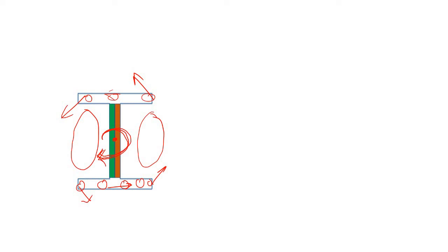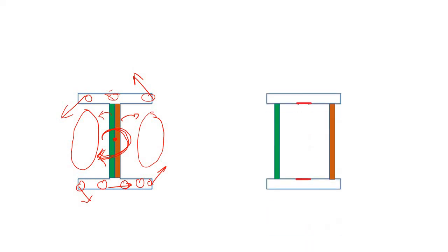So now again, if you simply split the web and put the parts further apart like this one, and now you apply the torsion like this, definitely at this point there is some material to carry the stress. At this point the material will carry the stress, and also in this zone, and in this zone, everywhere you will have some material to carry the stresses due to the torsion. So you can say that this shape is much more stable under torsion compared to this one.